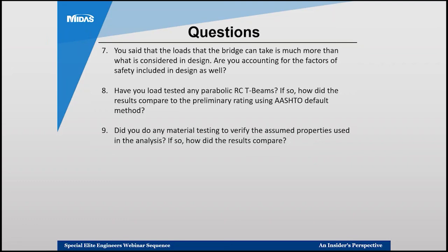But in some cases, if they want to test the material properties, it is possible, but I don't think it will change much. What matters is that you want to make sure that the reinforcement you have in the existing plans is what you have in your element in the field.